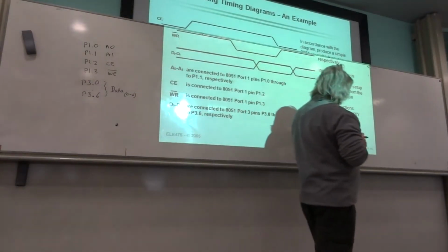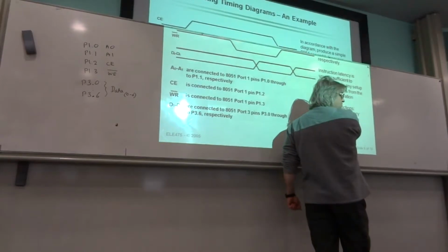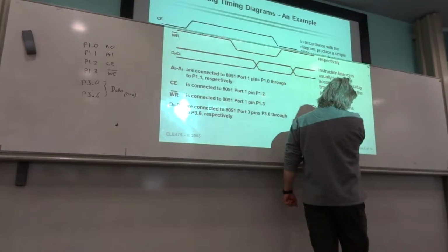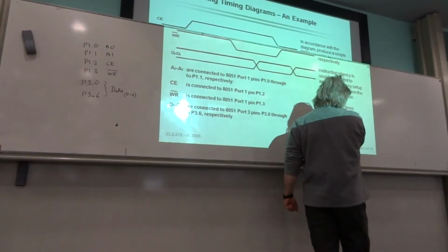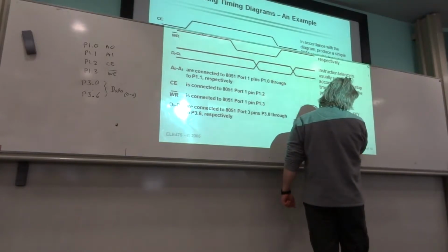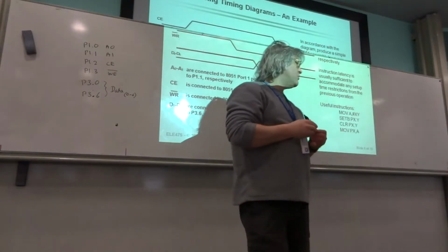And we've been given these instructions. So this is effectively immediate addressing mode to load a value into an accumulator, instructions for setting and clearing individual bits, and this is saying moving from the accumulator to a particular port to write a value to that port, moving a whole byte.